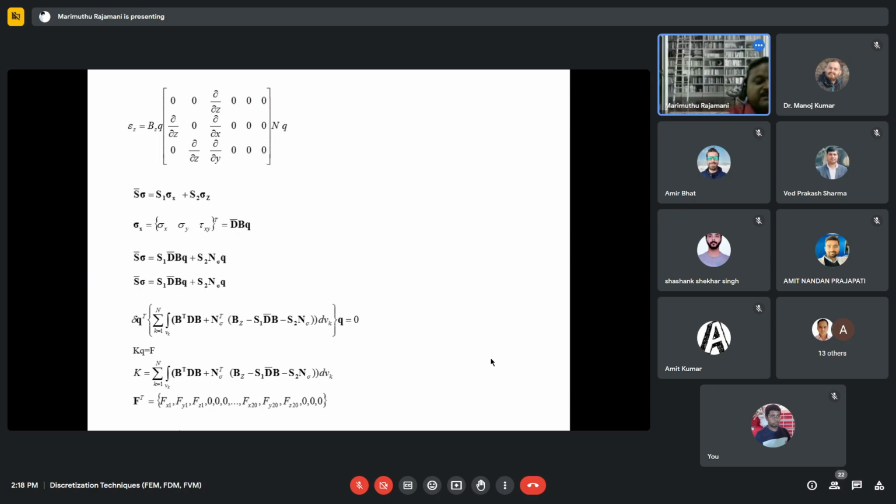And where interlaminar stresses are a degree of freedom, those locations are applied as 0 only. Loads are applied only corresponding to the displacement positions. So wherever the tau xz and tau yz positions are, they are made zeros in the force vector term.